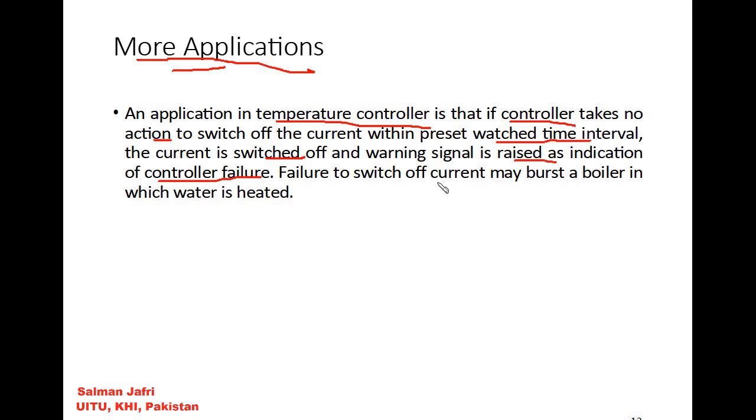Let's say we are turning on the current in a boiler, so we also start a watchdog timer, and the watchdog timer would overflow. Let's say if we want the current to be on only for 2 minutes, we set the watchdog timer to overflow in 2 minutes, after which the service routine would be called to switch off the current to the boiler. If we basically fail to switch off the current in our code, the watchdog timer would kick in after the 2 minutes timeout, and it would switch off the current. So it's basically a safety measure that we can have.